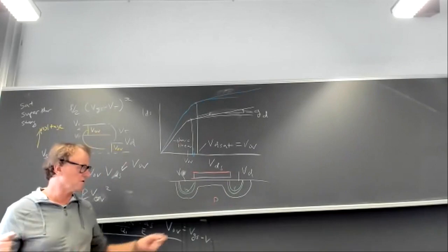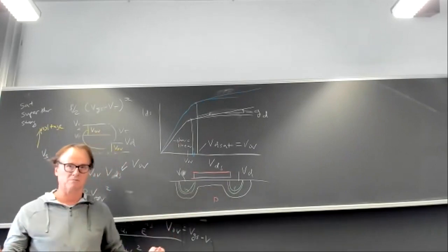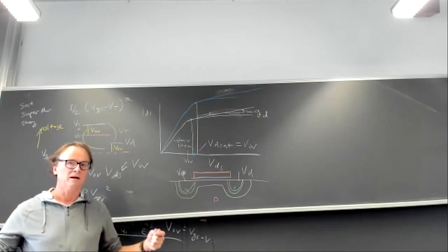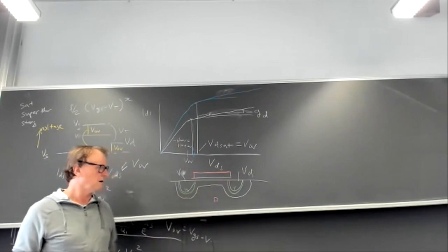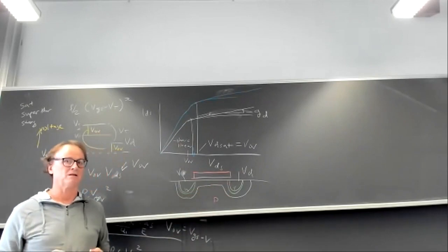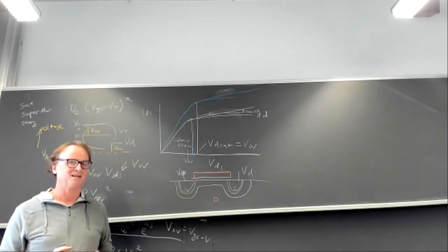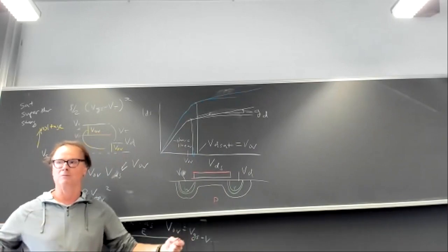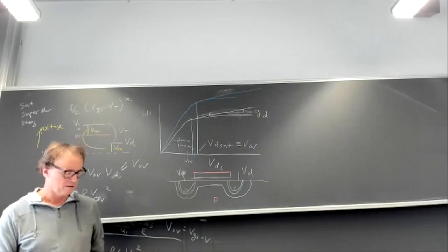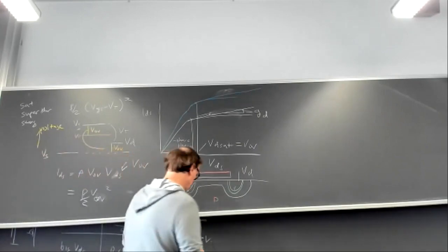The bigger the voltage you put across a p-n junction to reverse bias it, the wider the depletion region. It must be so because as you apply more voltage, that voltage appears across the depletion capacitor. And to get more voltage, you need more charge. And the only way you can get more charge is making the depletion region wider.